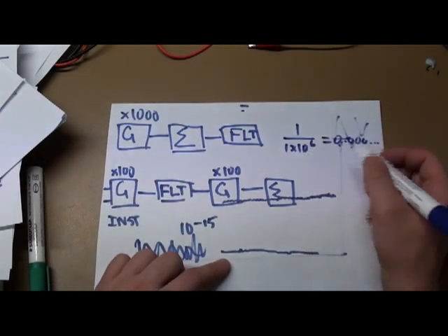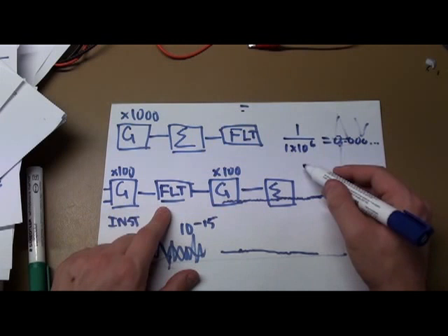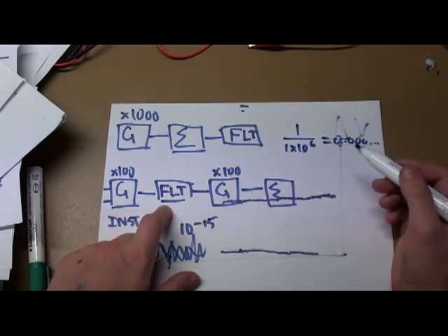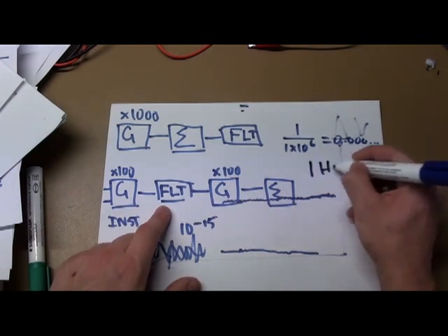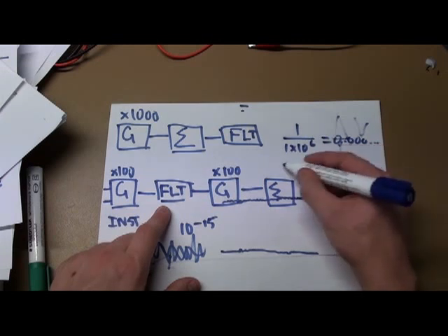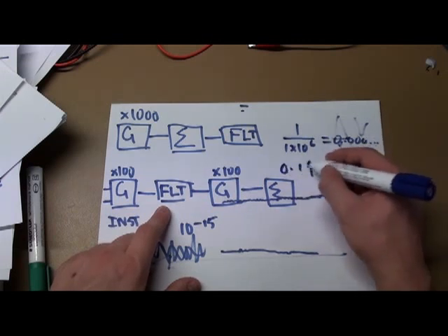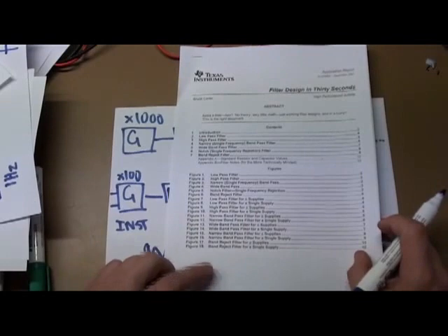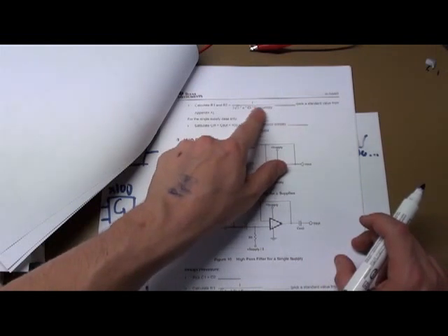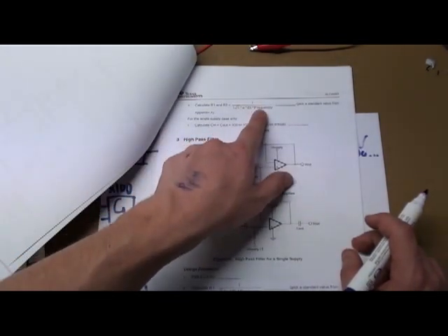And if you think about it, really we don't even want frequencies that are as high as 1000 hertz, 100 hertz, or even 10 hertz. I mean, really we want to start at getting all the signals below 1 hertz. And even lower if better, maybe 0.1 hertz. So back to our filter calculation document. In this formula we'd probably want something that was maybe 1 or 0.1, because our strain value is not going to change very quickly, but we know our noise values are very high frequency, so they're going to be changing heaps and we want to get rid of them completely.